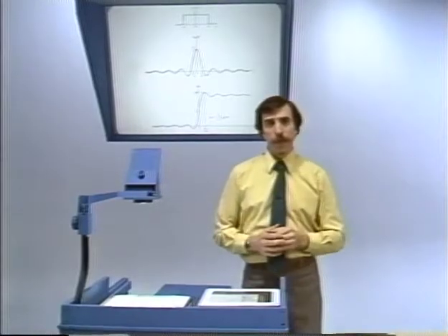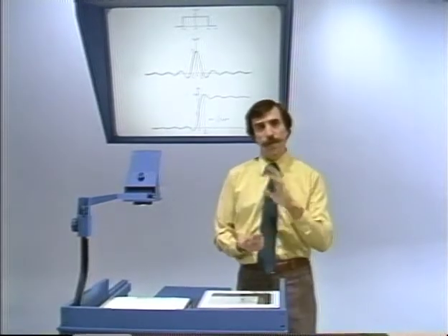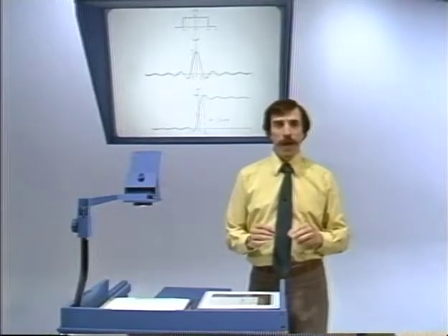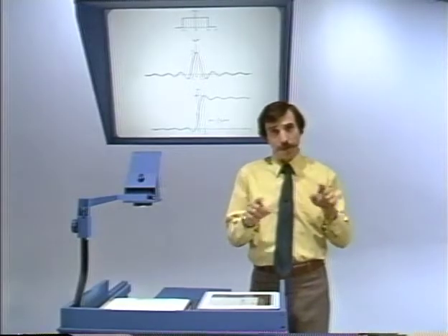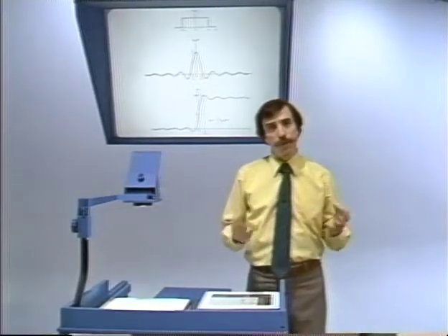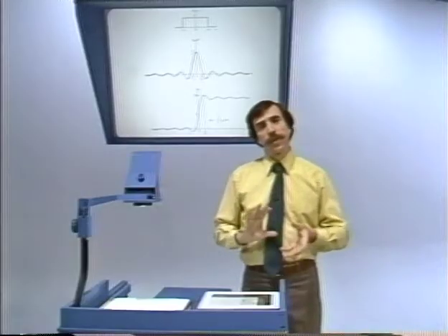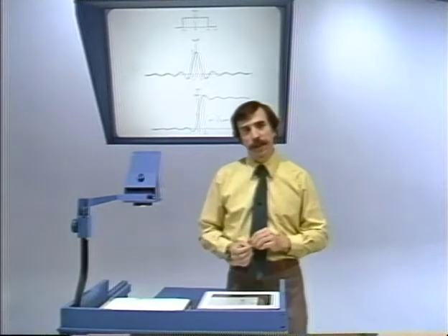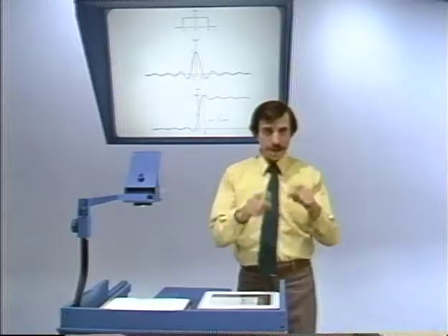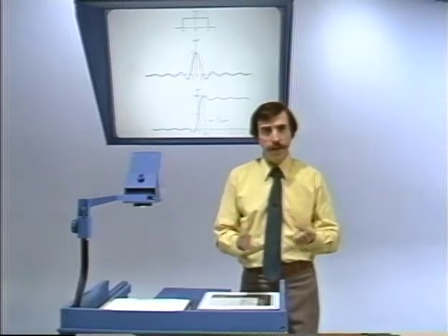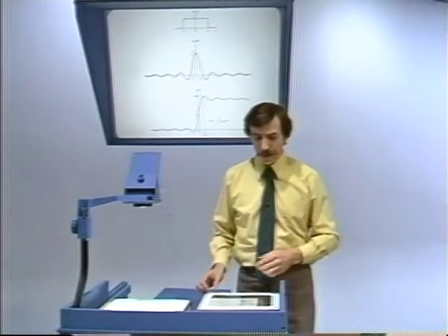That follows, among other things, from the fact that it's an even function. But keep in mind, in fact, that a sin x over x function goes off to infinity in both directions. So the impulse response of the ideal low-pass filter is symmetric and continues to have tails off to plus and minus infinity.